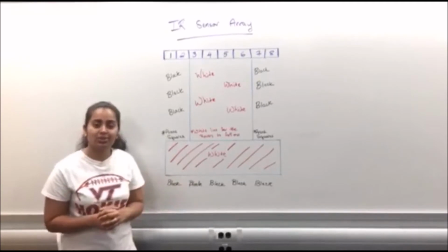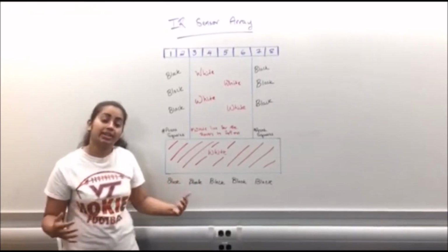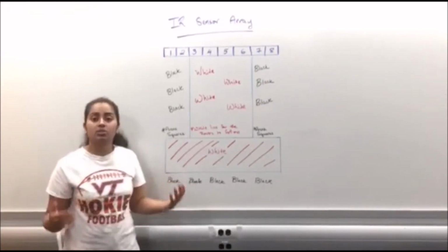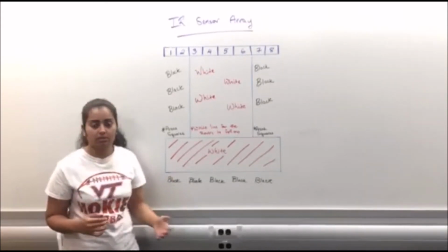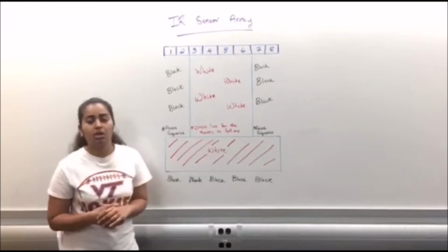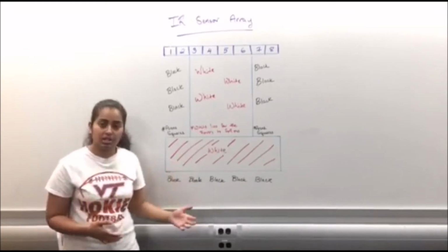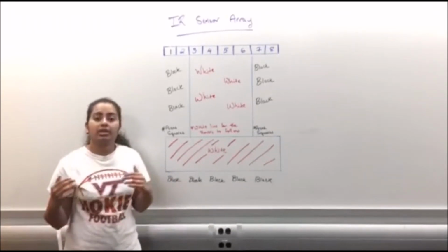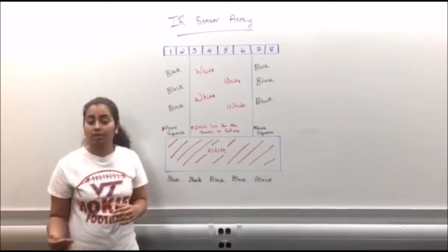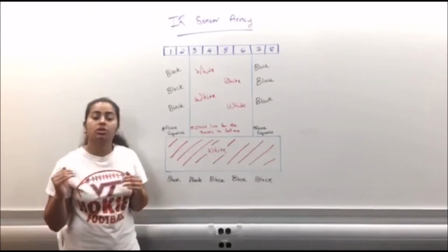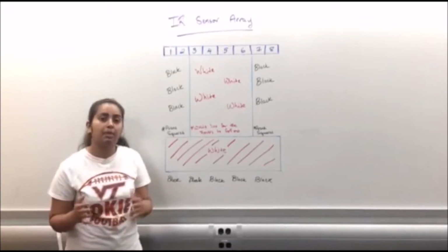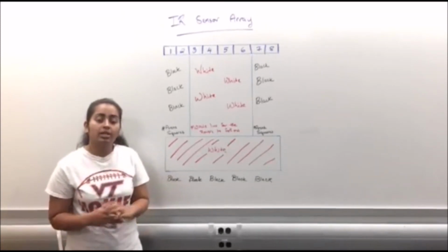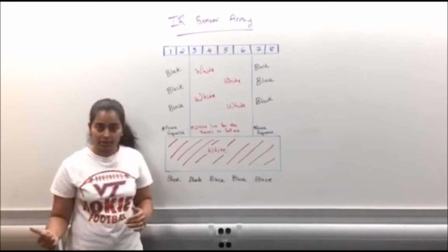For our sensors, we chose an IR sensor array consisting of 8 sensors. The way that the sensors work is that they shoot an infrared light onto the surface that they're looking at. They then charge a capacitor. So in order to measure the color that they're seeing, we have a timer interrupt that's triggered every 5 milliseconds that measures the time it takes for the capacitor to discharge. It then packages that information into an unsigned int and sends that to the sensor thread.